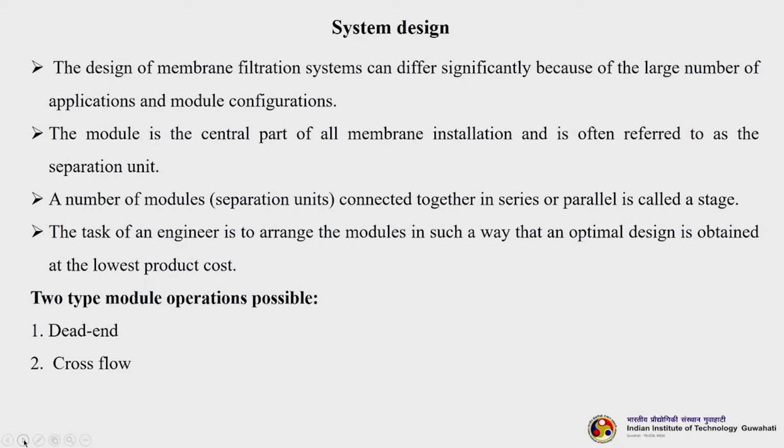The design of microfiltration membrane systems can differ significantly because of the large number of applications and module configurations. The modules are the same as we have discussed during ultrafiltration, or in general whatever we have discussed about modules. The module is the central part of all membrane installations and is often referred to as the separation unit. A number of module separation units connected together in series or parallel is called a stage.